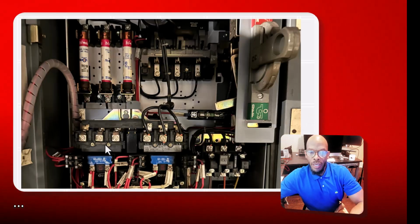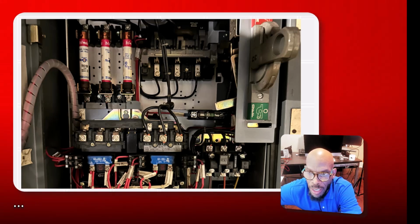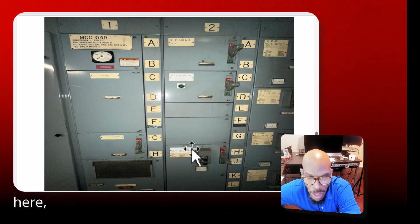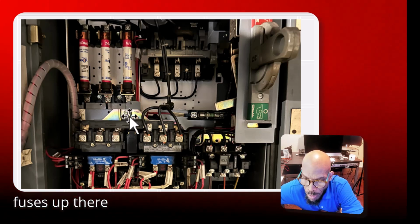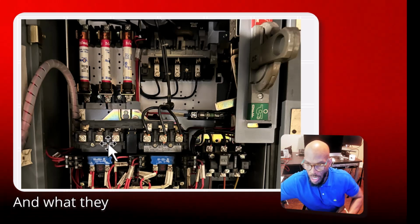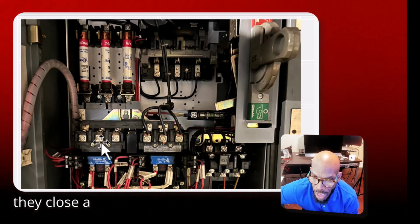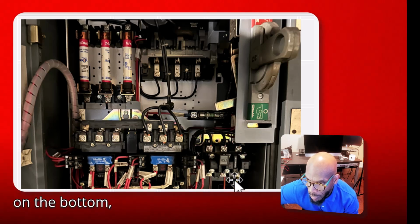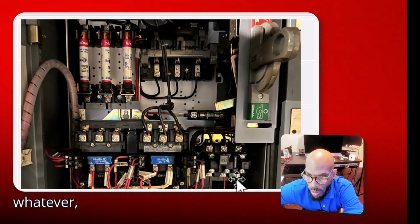Here, this is inside of one of the buckets. So if you open up one of these doors right here, this is what you will see. You've got your fuses up there, and you've got these motor starters, and what they do is when they get a signal, they close a relay, and then power comes in through the top and it comes out on the bottom and goes to whatever device it is, whether it's the pins or a motor or whatever.